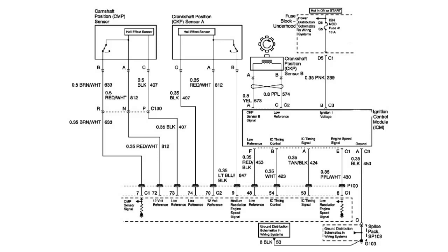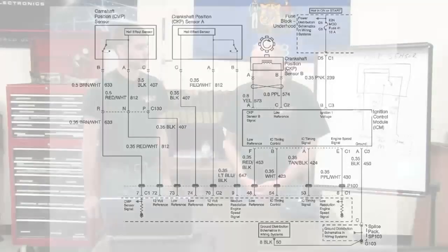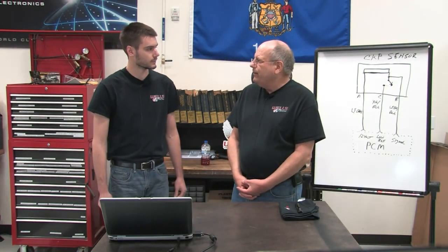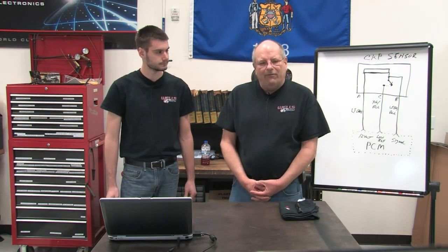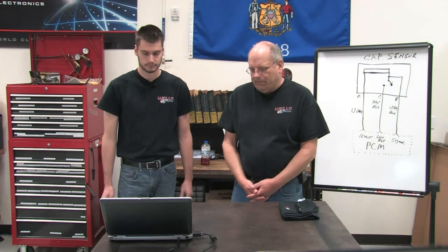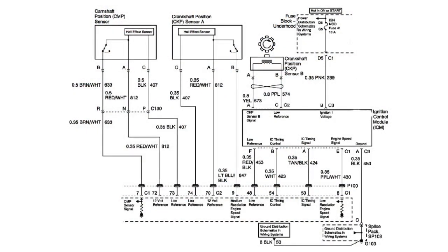And so that's what I did. I took our meter, went into power and ground, and I only had 11 volts. You know, that doesn't sound quite right. No, it sounds like we have an issue. As a matter of fact, if you look at the bottom of that wiring diagram where it goes to the PCM, it says 12 volt reference. We don't have 12 volts there. That's a problem. We dropped a volt. That could be a big deal in a big sensor world.